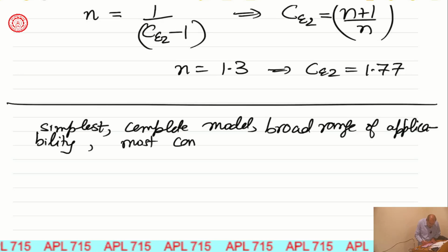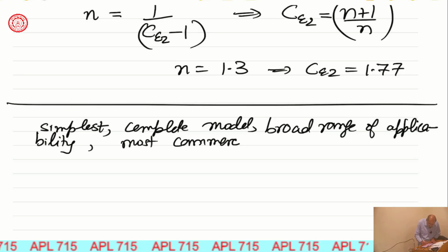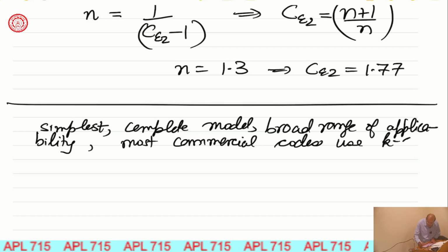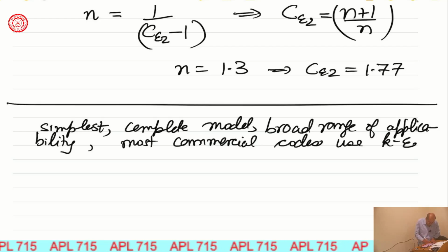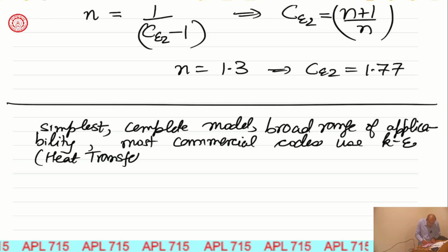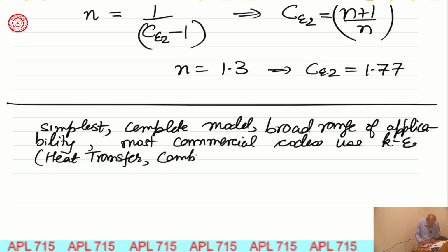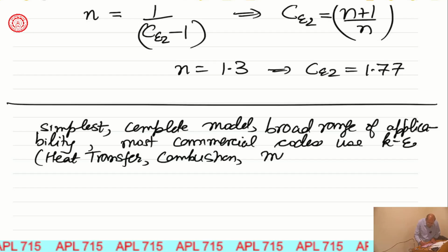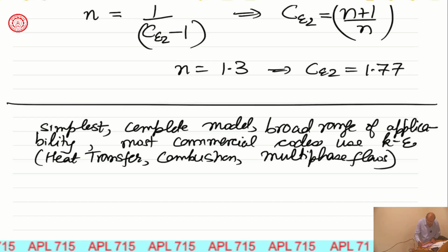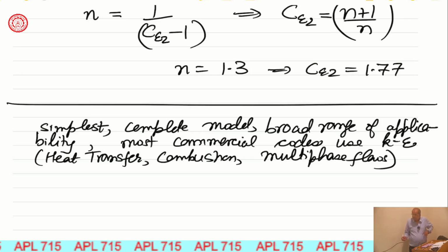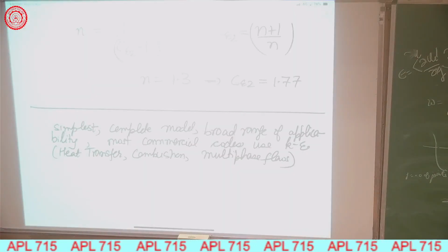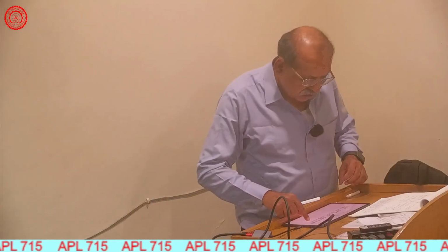Most commercial codes use the k epsilon model, and it has also been developed for heat transfer, combustion, multi-phase flows. So similar eddy viscosity model for the flux has been done, and it is quite useful.